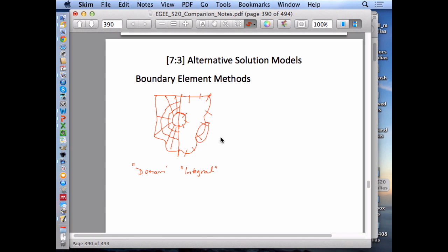And typically what they would look like would be basically two-noded elements that would represent the boundary contour, and we'd solve the system only on that contour. So you see immediately that if you're solving a flow problem, you'd have something like either complementary variables of fluid pressures or fluxes on those nodes, 1 degree of freedom per node. If you look at the degrees of freedom for the case where you have to volume fill with elements, you end up with a much larger system of equations. So you end up with many more equations in this than you do in integral methods.